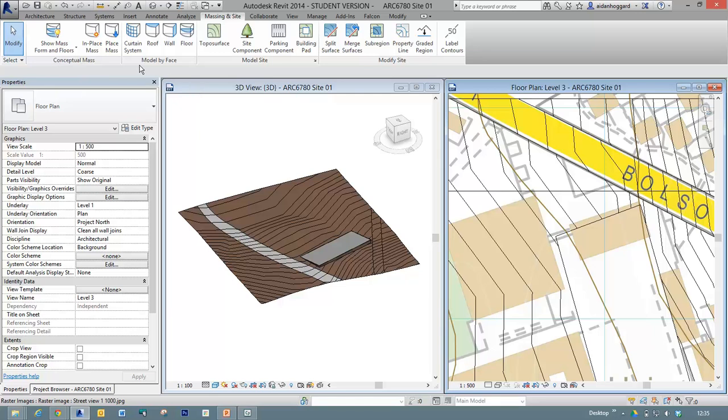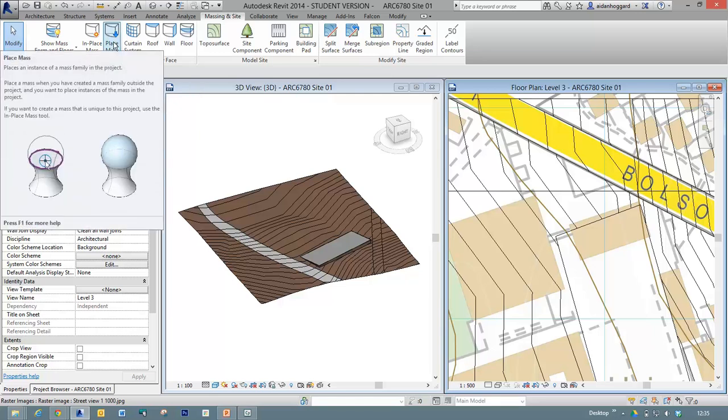Sorry. Yeah. In the property window of building pad, the default level is level 3. It did default to level 3 probably because that was where I previously set it. So you can change it. Yeah. I mean, at the moment our levels don't really mean anything.